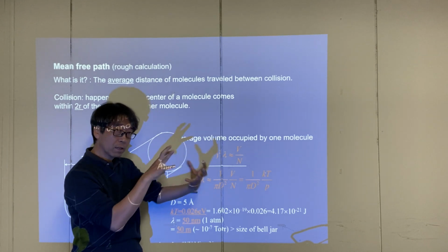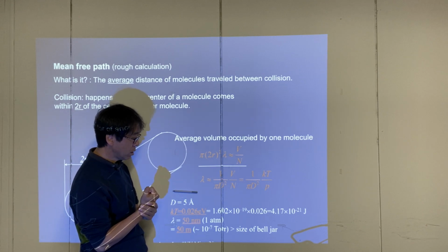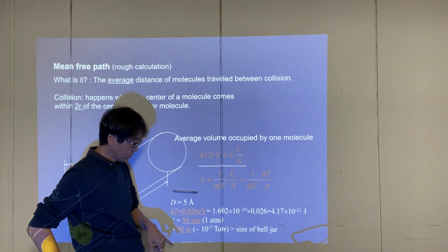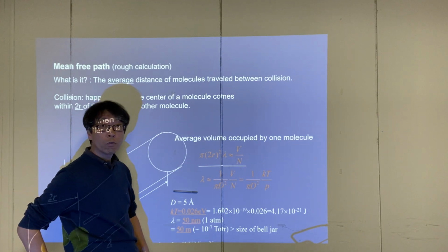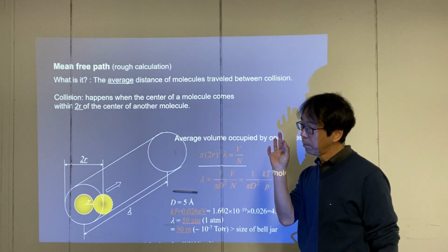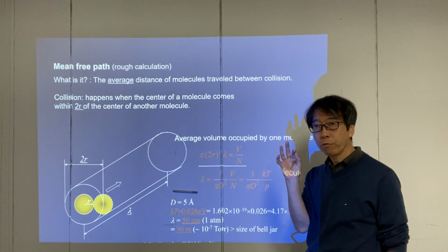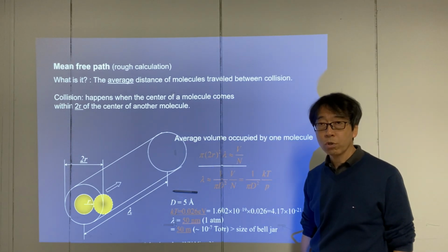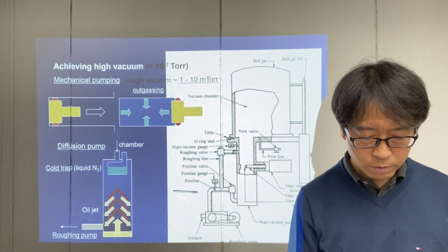It's like a cloud, like a gas. But if you maintain the vacuum at a high level, 10 to the minus 7 torr, the mean free path will be as long as 50 meters. In other words, this little metal atom will travel 50 meters before it hits another molecule. So this travel path will be super straight. That's the beauty of this deposition.